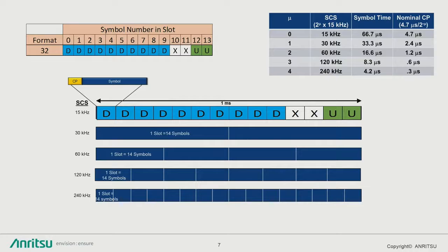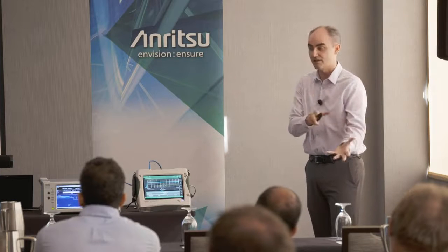No, no, no, it's downlink. I can't use it, throw it away, and now you have timing errors. That's all based on the symbol time, right? As I go down and do higher and higher subcarrier spacing, you'll notice that I get way more symbols and my timing becomes even more critical, okay? So if you were off by just, let's say, 5 microseconds, I think that's the spec, right? 5 microseconds throws you into a completely different symbol at 240 kilohertz spacing, okay? That's how the correlation between timing and FDD actually occurs, okay?